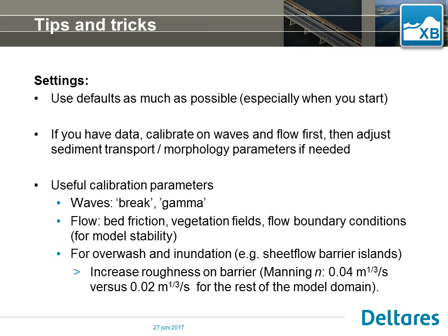When getting started with XBeach, we really recommend that you use the default model parameters as much as possible, especially if you don't know what the model parameters do in the model. The best way to ensure that you're using the default values is to not define a model parameter in the params.txt file. So if XBeach can't find the definition of a certain model parameter in the params.txt file, it will automatically choose the best default value for that parameter.